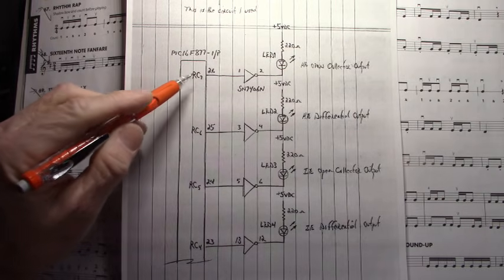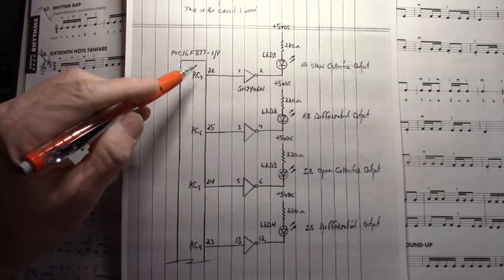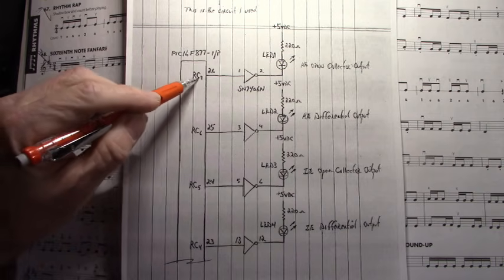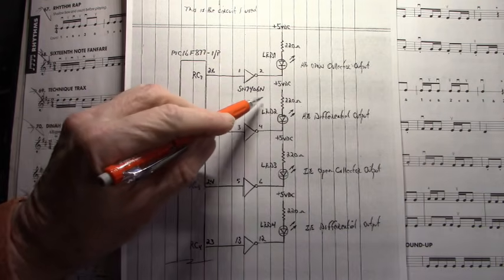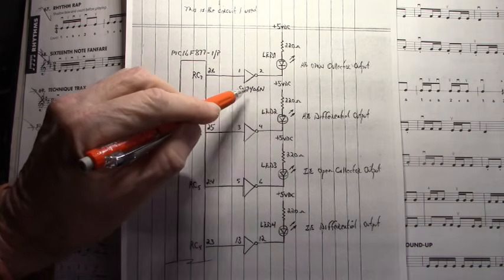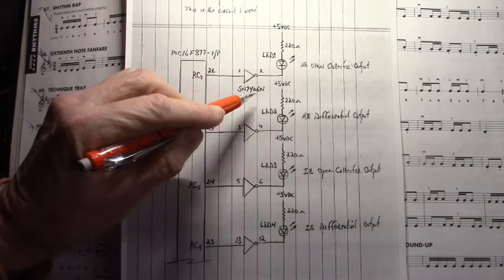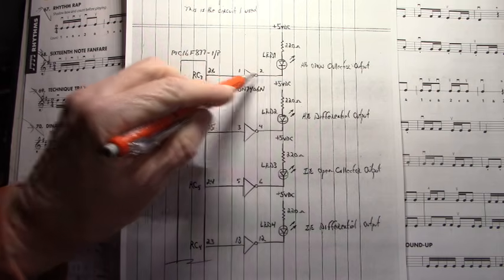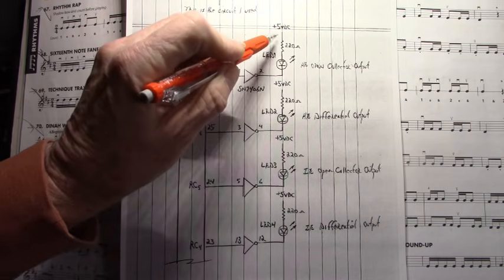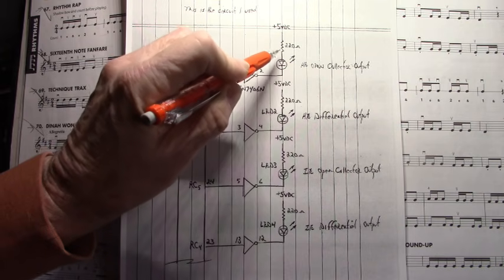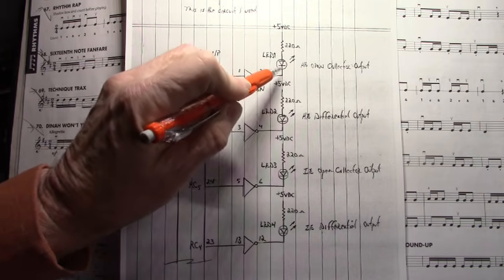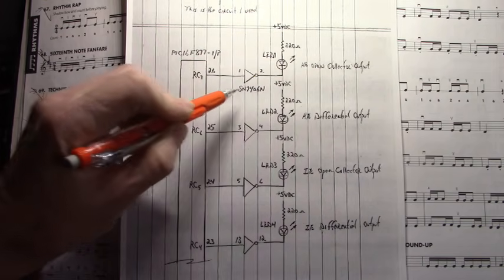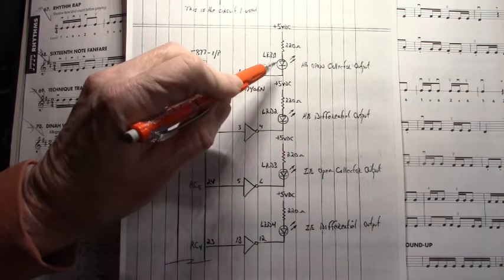And so what we do is we apply a high on pin 26, that's port C bit 7 to this 7406. This is an open collector inverter, and that pulls the cathode of this LED to ground so that current flows through this 220 ohm current limiting resistor from 5 volts through the anode cathode junction to ground inside that 7406, illuminating that LED.